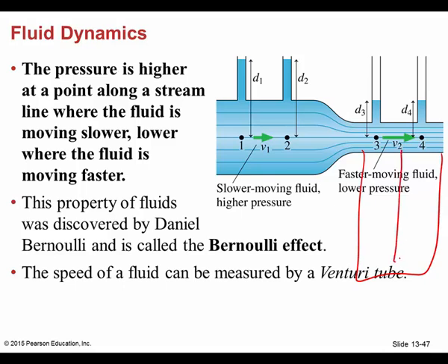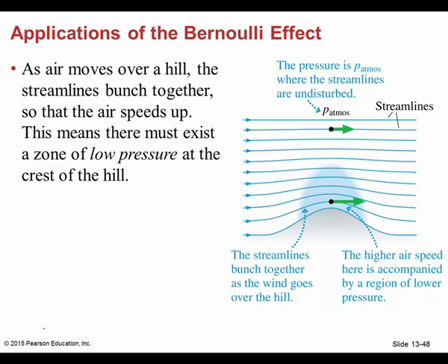You've got your tube going down in here to pull the gas up, and then you've got your little needle valve. It's got a screw on the top of it. The fuel is sucked out of the gas tank by this lower pressure, because there's an area of low pressure here, an area of high pressure there. In a carburetor, it's called the Venturi effect, the Venturi of the carburetor. But it's basically based off the Bernoulli effect.